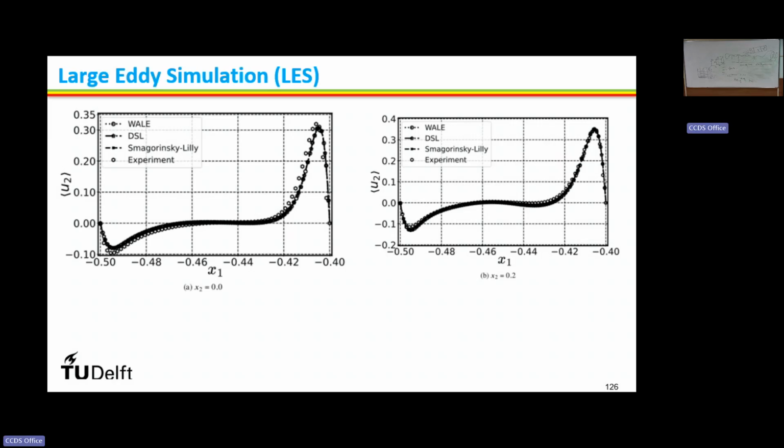No, time step has influence. You should choose your time step in such a way that it resolves the eddy turnover time, right? You are trying to capture the movement of the small eddy. You should have a time step that is less than the turnover time of the eddy. If you take a small length scale and a large time scale, do you think you can capture the small eddy?